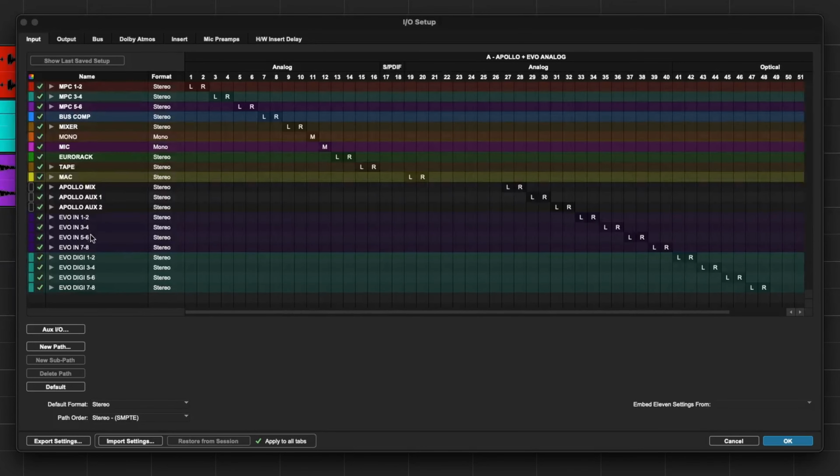All the individual Evo inputs. So inputs Evo 1 and 2 would be the mixer inputs basically here. Exactly the same sort of thing. But this mixer is post Apollo, whereas Evo 1 and 2 is the input signal, the analog input signal of the Evo, whereas the mixer version here is the ADAT version, so the digitally converted version, which means it goes through the console app, so I could, if I wanted to, put some processing in on the way in.